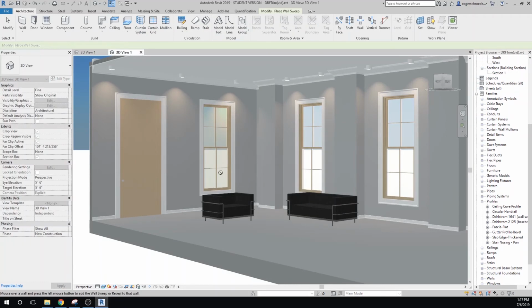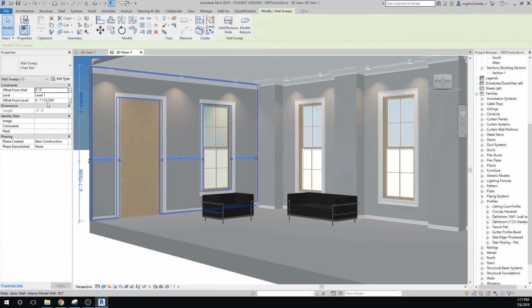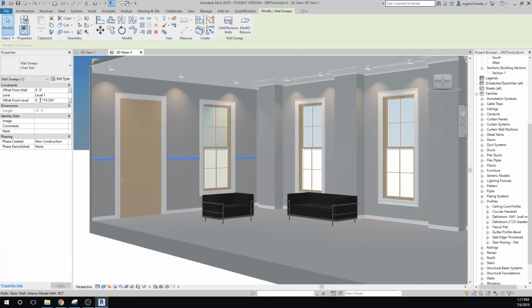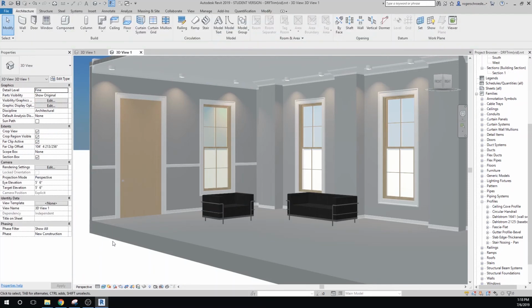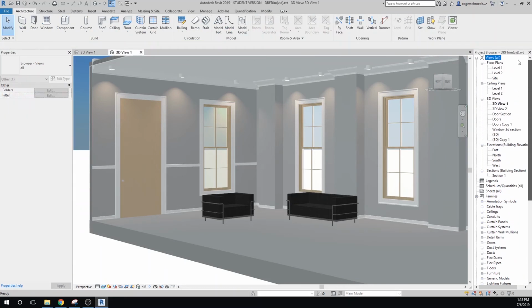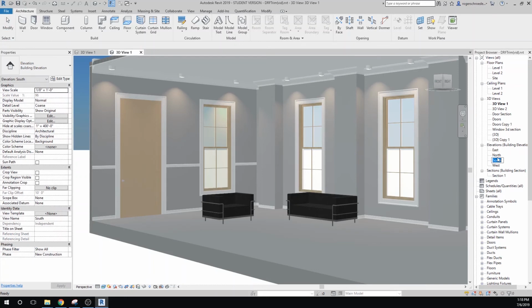And we're able now to actually import that into our document. I wish that would show up right away, but you have to click it off. If you want to adjust the height of this, you can do an offset level from the base of it. Or what might be a more acceptable way to look at this is to slide to a front elevation and create a new level.